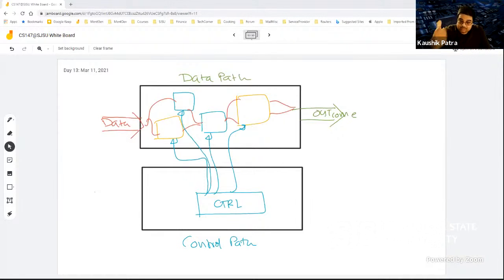Other than that, we have load word and store word, which involve the data memory, and also jump and link. No, jump and link is a J-type. It has one or two other different ones. I forgot at this point, but we'll see. The point is that with all this complexity, you need to use more multiplexers in the I-type data path.